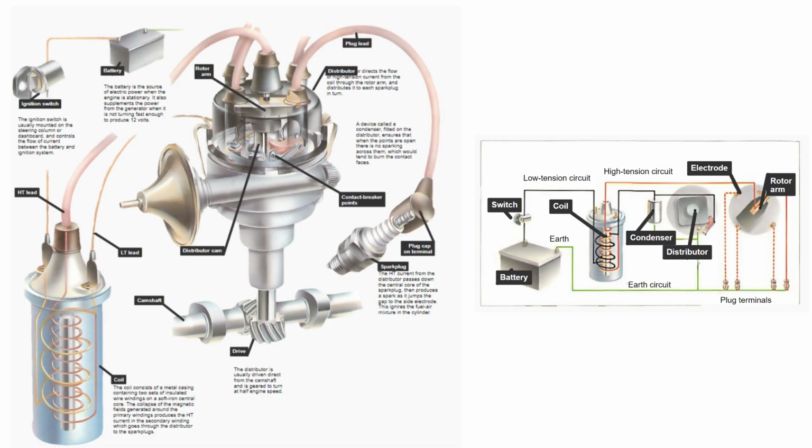Working principle of the ignition coil. An ignition coil is made up of a laminated iron core surrounded by two copper coils. It is different from a power transformer, as in this there is an open magnetic circuit. The energy collected in the core's magnetic field is the same energy that is given to the spark plug. The primary winding has fewer turns of heavy wire.